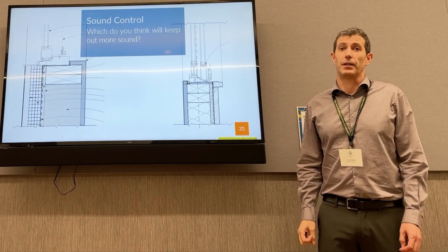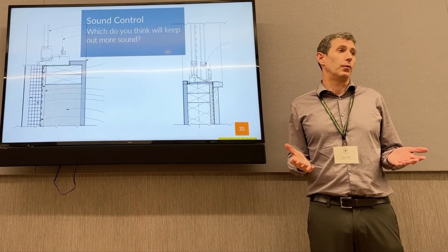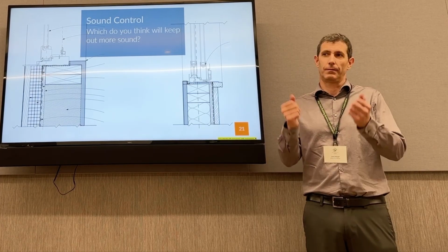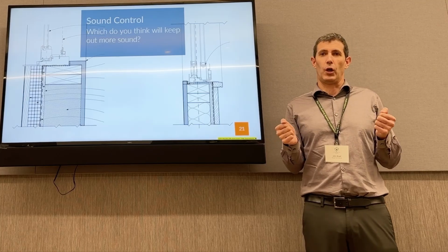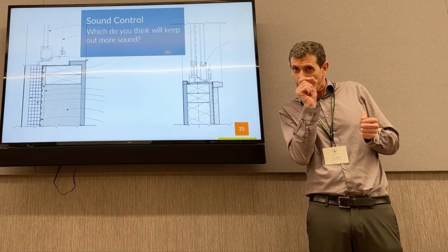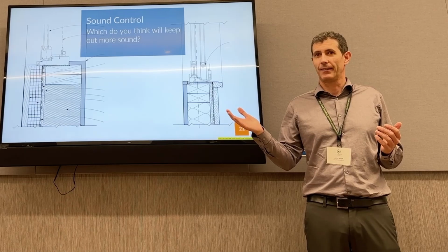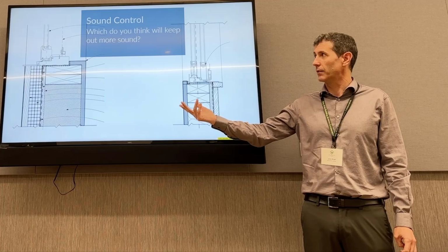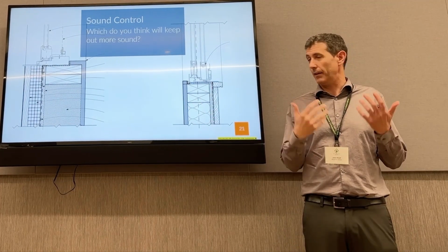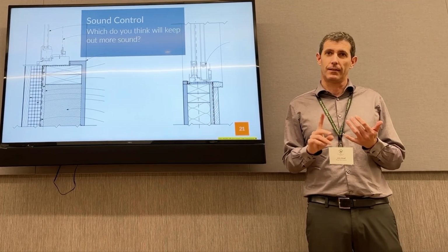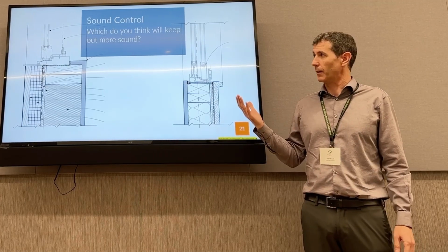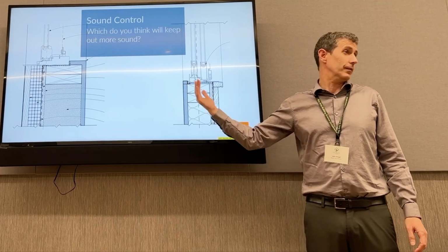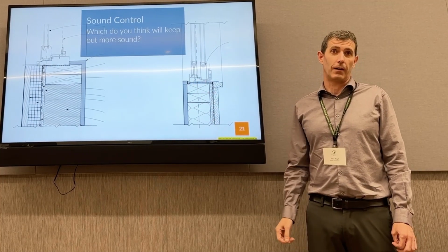So this sort of speaks for itself. The thicker and more substantial the walls are and the less holes they have for sound to go through, you can have the most soundproof window in the world. Open it a quarter of an inch and you hear everything, right? So eliminating holes and having thicker, more substantial wall sections and double pane windows, and you can put in laminated safety glass and all these other things to cut down sound. You get a much better sound performance out of a new home than a remodel typically.